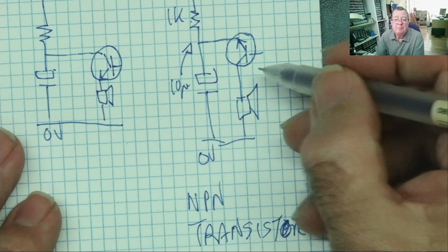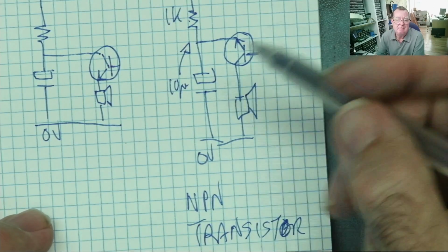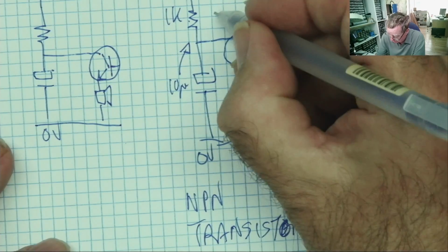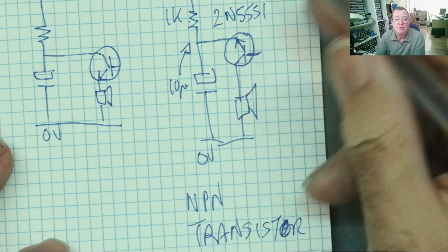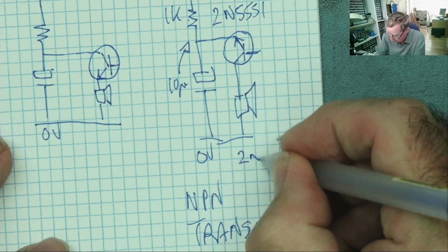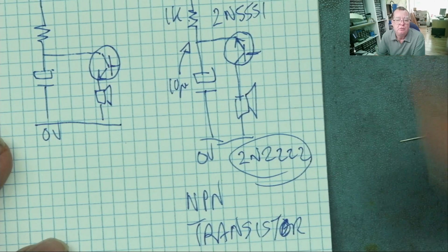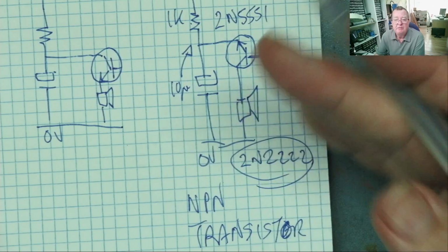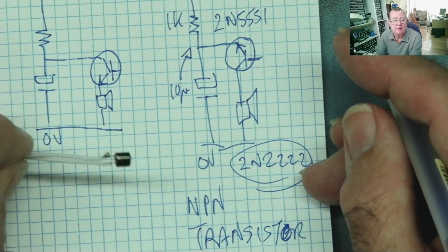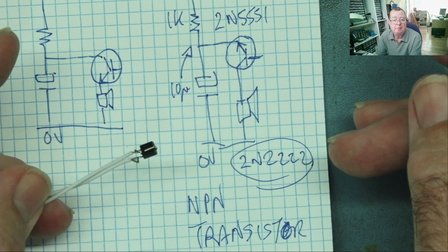So we're using the fact that the transistor will break down in the reverse direction at a certain voltage. You can't do this with all transistors. Some work better than others. I use this one. Apparently you can use a 2N2222, but I tried this with 2 or 3 of them and it wouldn't work. So experiment if you want to build this with different transistors, but you can see this one worked really well to demonstrate the property.